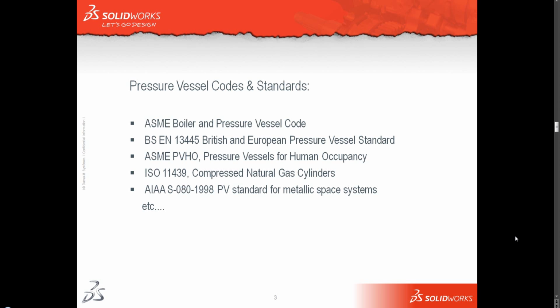This list goes on and on, and the reason I'm going through this is because it's down to the engineer to know what is relevant. Unfortunately, I'm not going to unleash some revelation that SolidWorks has all of these codes built into it. Far from it. The engineer has the responsibility of knowing which code is relevant and which articles within the code are relevant and how they can comply with those. What SolidWorks Simulation is going to do is allow us to conduct stress analyses and gather out the relevant pieces of information for comparison with our pressure vessel codes and standards.